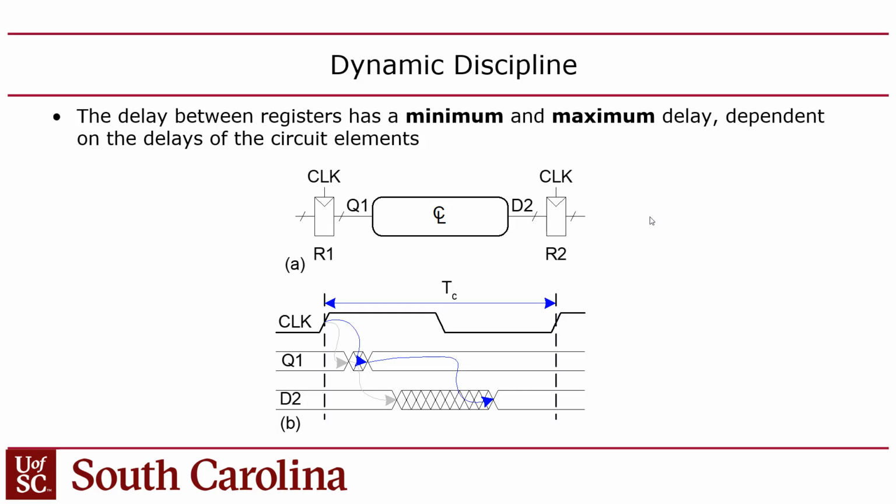So in your branch instruction, you start with instruction EX. That takes the register addresses through the register file, which is asynchronous, so it's combinational logic for all practical purposes. The registers come out of the register file, then they go into the ALU. Then you have to subtract them to figure out if you want to take a branch, whether it's a branch if equal or a branch if not equal.